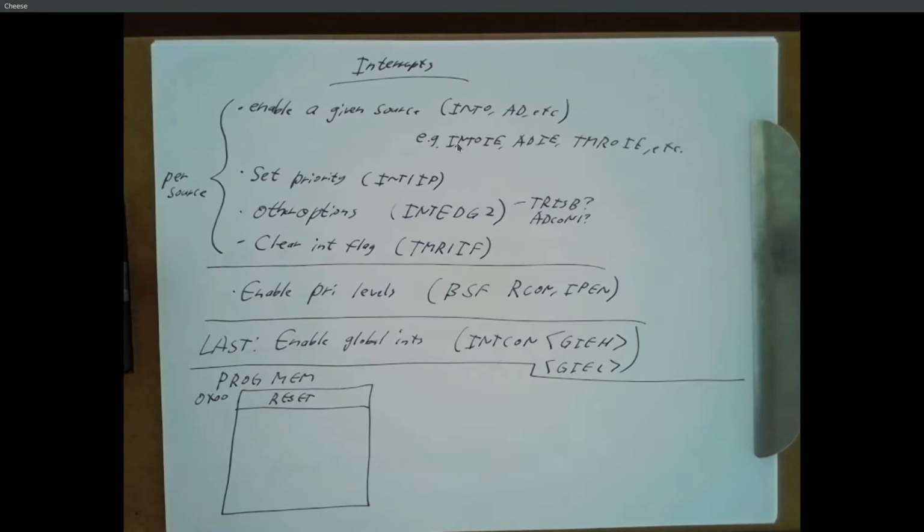That's where your code begins. Doesn't matter what you write, doesn't matter how you say org, doesn't matter if you have interrupts. When you power on your processor, it's going to start with instruction 0. If you haven't put something there, it's a gamble what's going to happen.